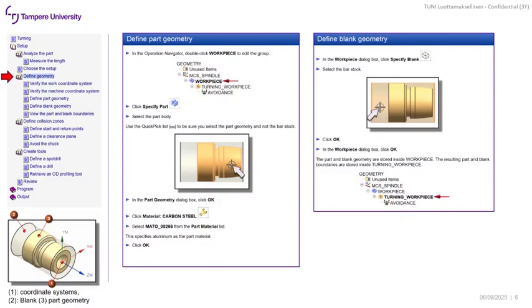And also you superpose another component, for example in the assembly, that defines your raw stock. So here is just a simple cylinder, but of course it can be any shape that is actually available in the workshop that you're going to use. This is one option. So you are defining these two geometries superposed on top of each other, or inside of each other, in the CAD file, in the assembly file, and you save it.